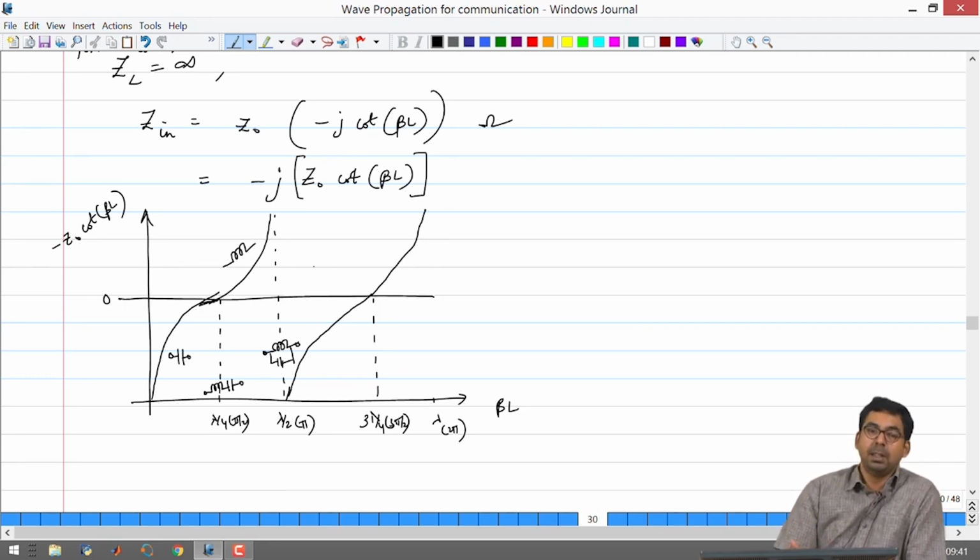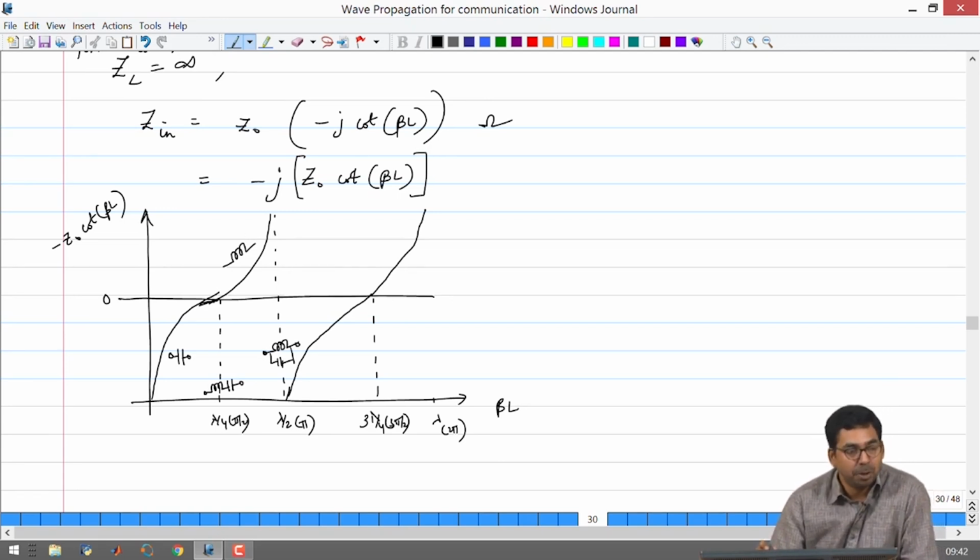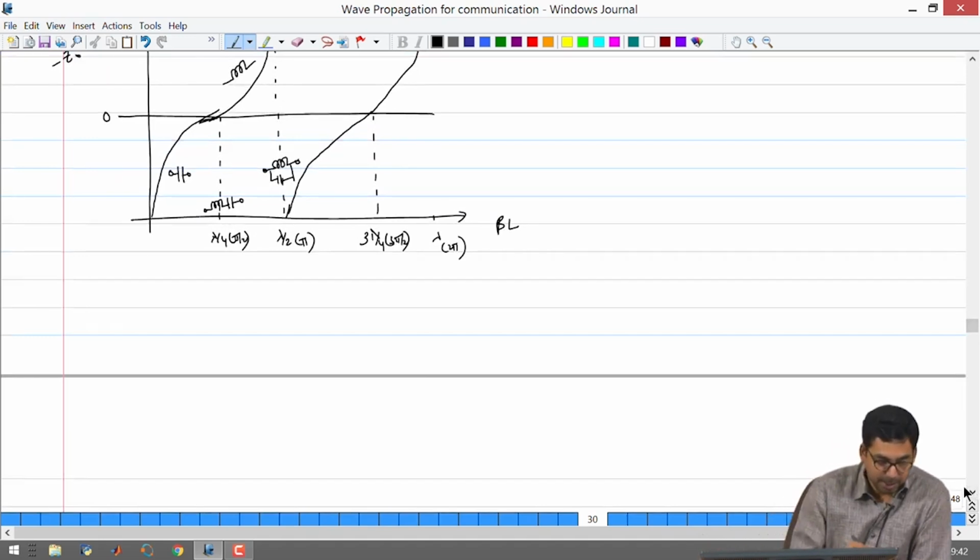So, it means that the technology for making inductor is not different from the technology for making capacitor. You will be making the same transmission line in your manufacturing company, but depending on the requirement for that particular case, you will be precisely dicing or cutting your transmission line to where you want, alright. So, it means that I can have L, C and parallel combination of L and C. So, you could build a lot of circuits with this, alright, and all you will need is transmission line and cut with different sections.